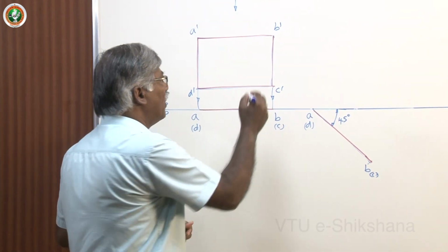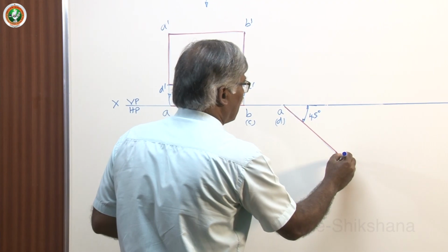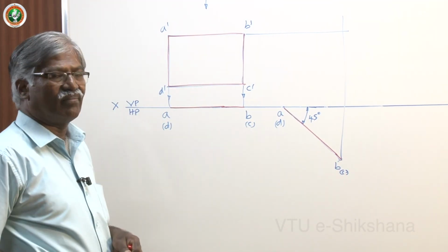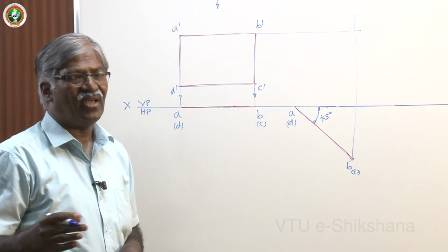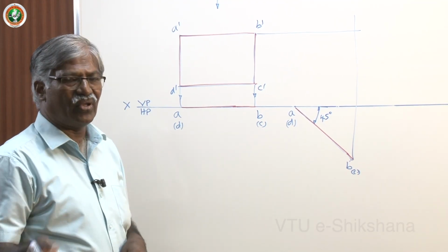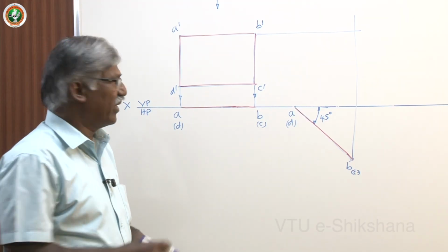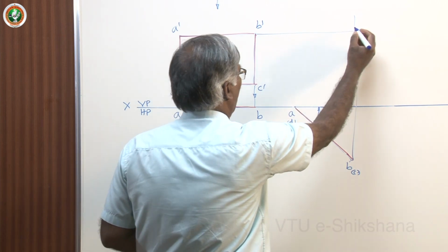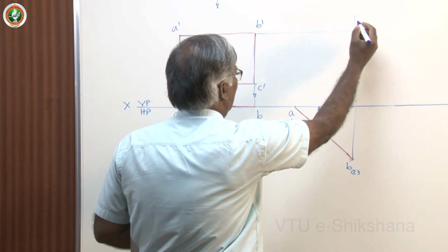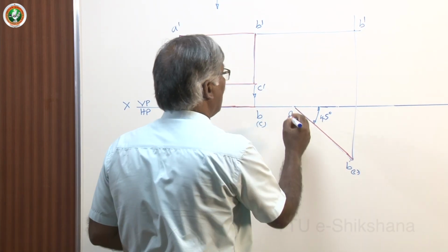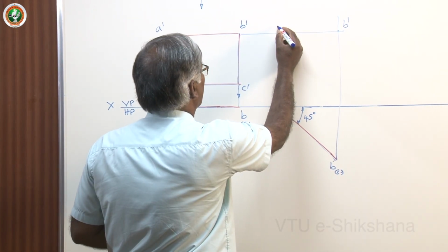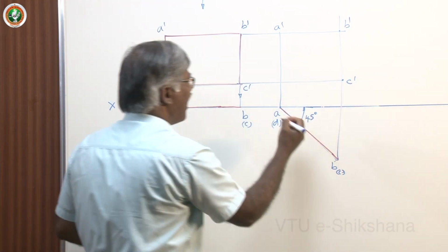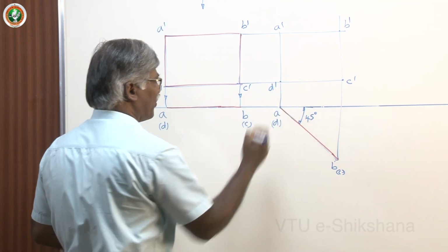Second figure, front view. Try to draw the right extreme projection and then the topmost projection. You should not cross these lines when using manual drawing. In case of computer, you use the alignment indicator. You touch this point, move, again touch this, and you will get the point. Then this point is B dash. This is A dash. Here you have C dash and D dash.